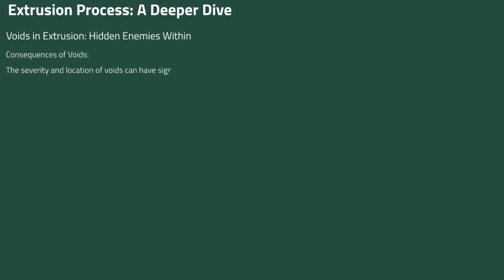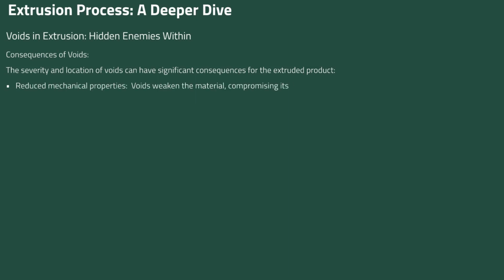The severity and location of voids can have significant consequences for the extruded product. Reduced mechanical properties. Voids weaken the material, compromising its strength, stiffness, and fatigue resistance. This can lead to failures in critical applications.